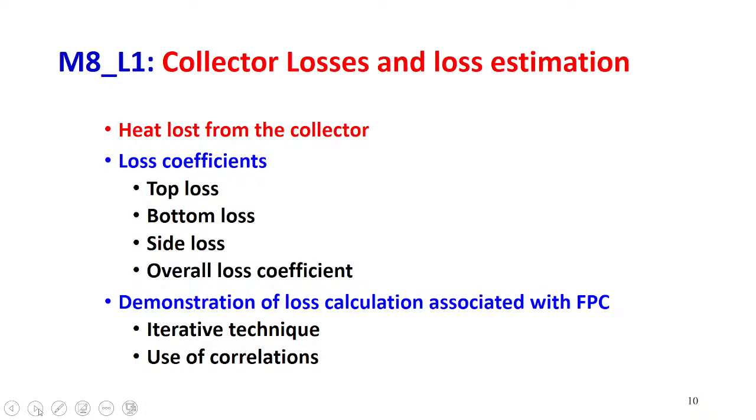In lecture 1 of module 8, we have primarily discussed collector losses and loss estimation. So, what are the loss coefficients like top loss, bottom loss, side loss, overall loss coefficient, and also we have demonstrated the calculation by using iterative methods and correlations for this heat transfer analysis.